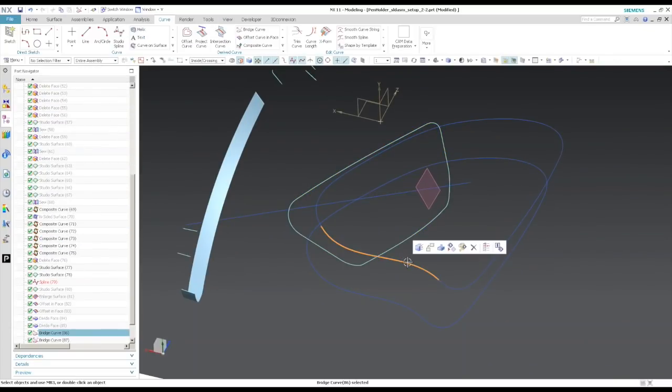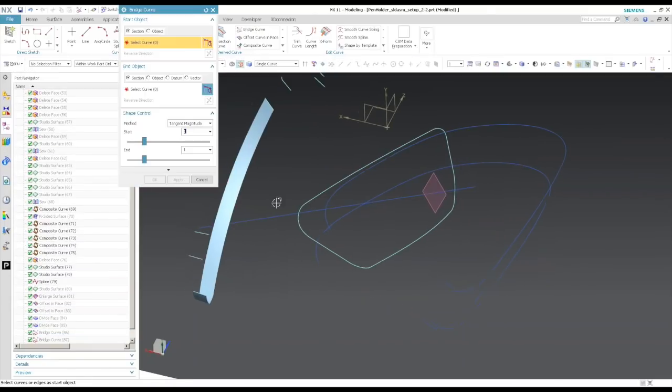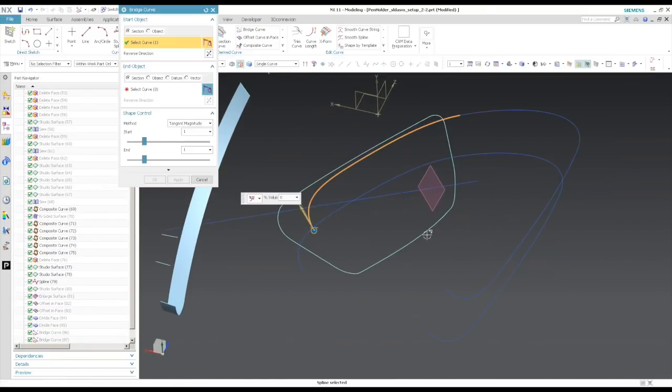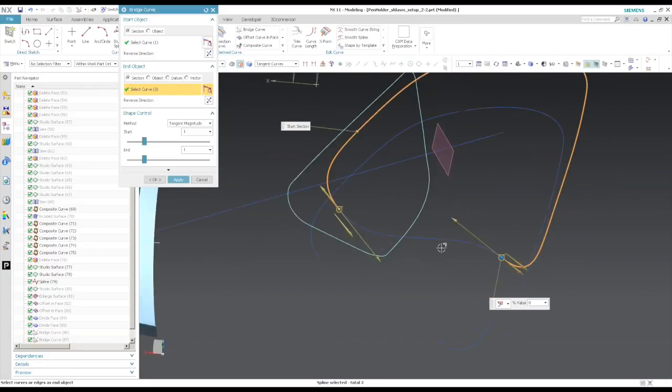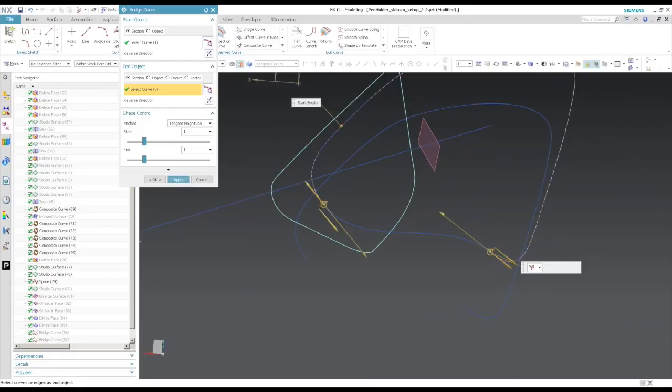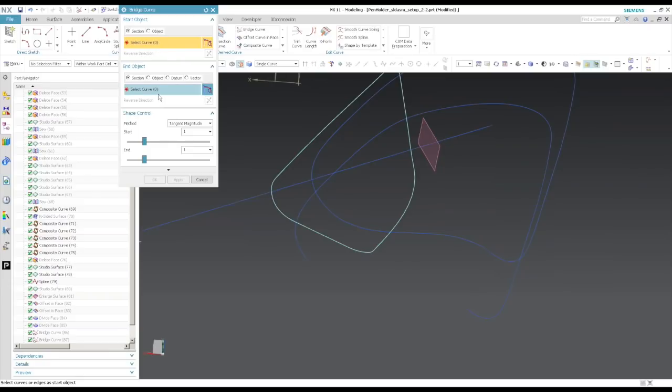So I'll show you. That's kind of a cool command. So I'm using my middle mouse to say accept. So I'll hide those to show again. I click the line, click the center mouse, click the next line, hit apply. Now when I do that again, the center mouse will move to the next box and hit apply without closing the dialog.